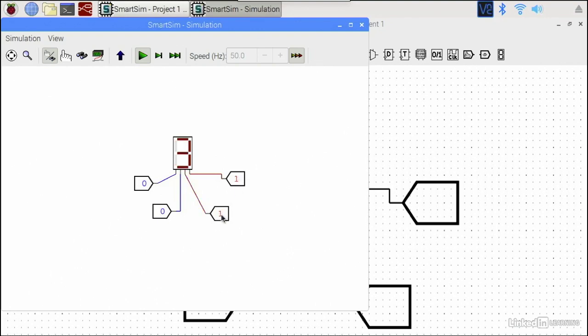Do you understand the relationship between the push buttons and the display? Yep, the display is showing the hexadecimal value of the binary states of the push buttons. Why do you suppose you get F if you turn on all the buttons? And how would you display a C?